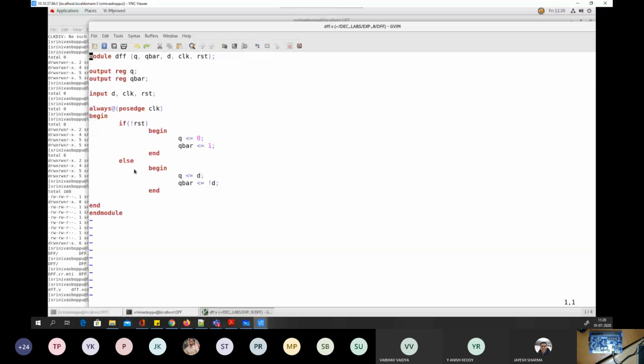So now coming to this, let's look at the D flip flop again. As I said, module and endmodule are the keywords. It's like a class definition. Whatever logic you need to describe, you describe within these two statements. Then the module identifier could be anything; I just chose DFF, and then within brackets there are different styles of describing these names. This is very simplistic: you can just have signal names defined. You don't mention whether it's an input or an output here; you just declare what the signals are.